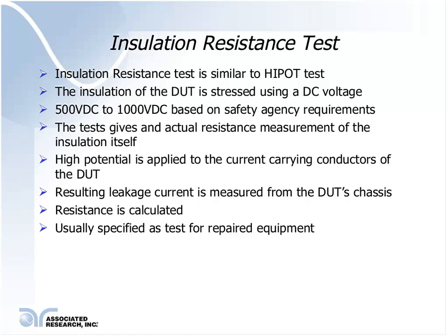This way, the insulation is stressed, and the IR tester measures the leakage current on the exposed metal chassis. Then the IR tests are usually specified as a test for repaired equipment just after electrical devices have been repaired. It is a good practice to run an insulation resistance test, and it will give us some good quantitative data about how the repairs were.